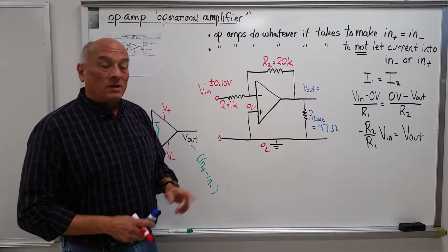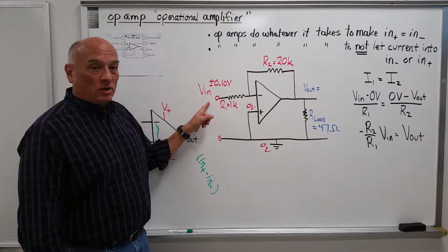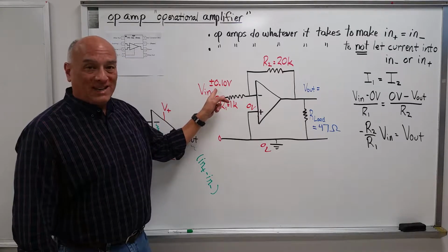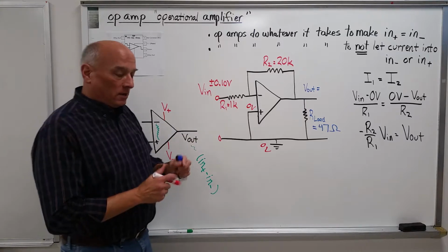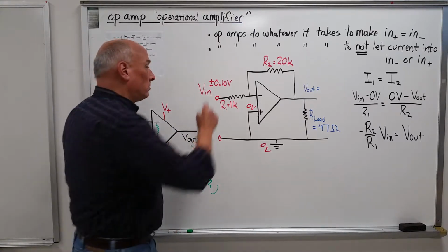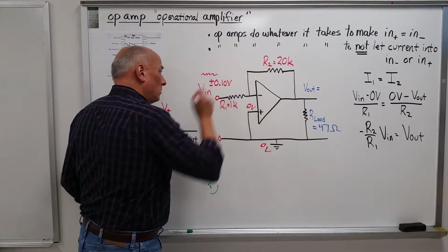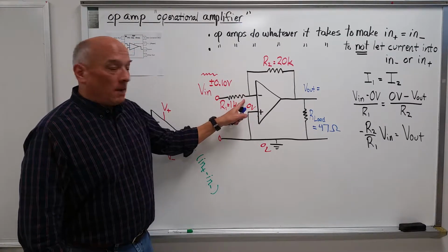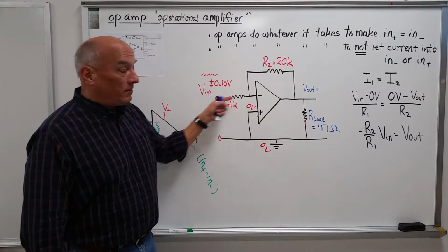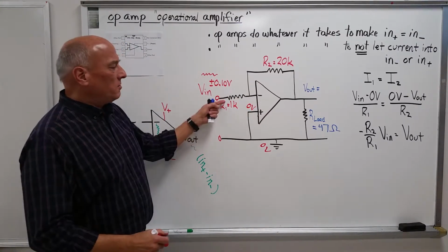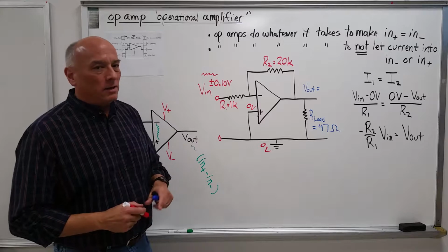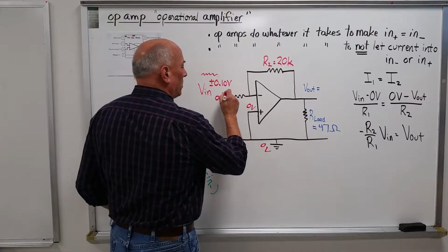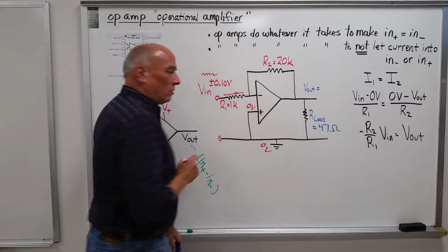Now think about the physical consequences of this. I'm going to take my function generator and put a plus or minus 100 millivolts, or 1/10 of a volt, sine wave signal into this. I'm doing this so that I put it across this resistor and drive current through it. Now you know the current goes first one way and then the other, but I'm just going to look at the current going this way first. So there goes the current, through the resistor.